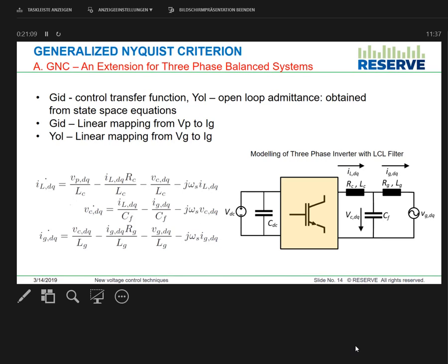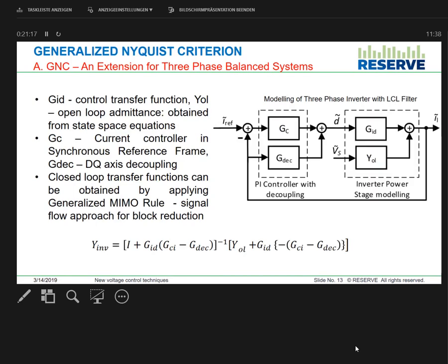And this omega times I is the exact term that needs to be eliminated. And that is what we do here. With the opposite sign, we try to cancel it out. That's the idea, so that D and Q are completely decoupled. Any change in D would have very minor effects in Q, because our assumption is linear systems, but in reality it's non-linear. So you are only trying to kill the linear terms, but there could be non-linear terms which somehow show as an impact. So you are not completely eliminating, but to a good extent.